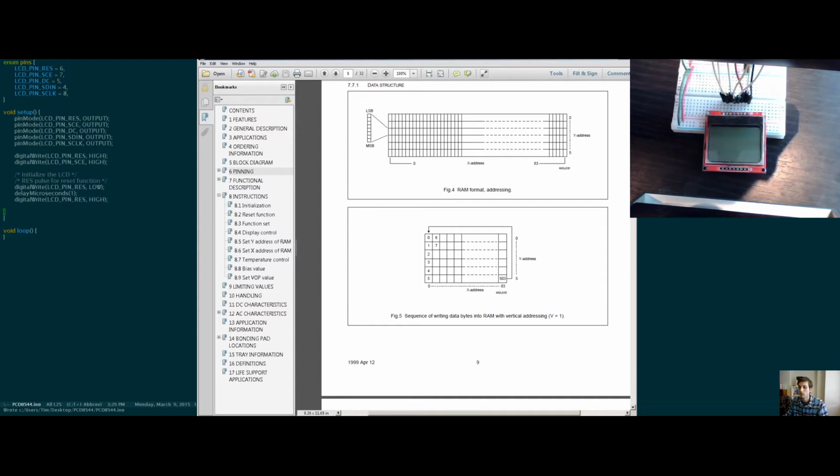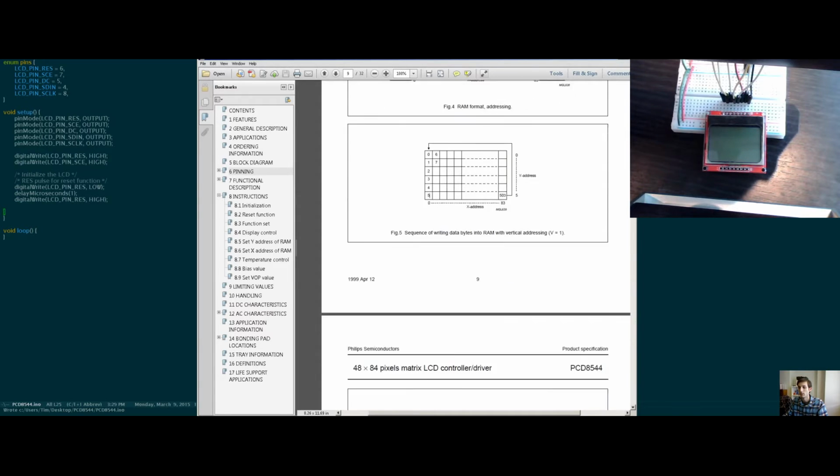So this is the vertical addressing. If we write the first one, the next address is the one below it, and then below that, and below that, and when it reaches the bottom, it wraps around to the top of the next column. But if we're writing text to the LCD, because we want to write hello world, then this doesn't make a whole lot of sense, because this means the text would go from top to bottom, and then the next column top to bottom, and so on.